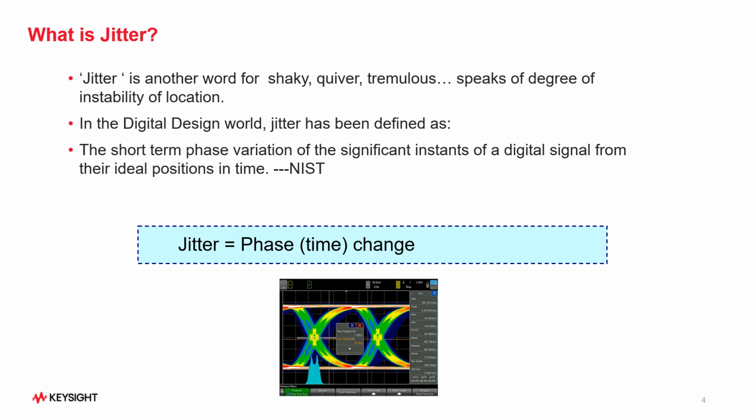Jitter is a word which is associated with instability. The definition of jitter by electronic engineers is something like this. A simple definition would be: jitter is the time difference between when a predefined event should have occurred and when it actually did occur. The time difference is expressed in unit interval, or UI, and 1 UI is the value of the bit period of the ideal clock signal. This time difference can be treated as phase modulation.